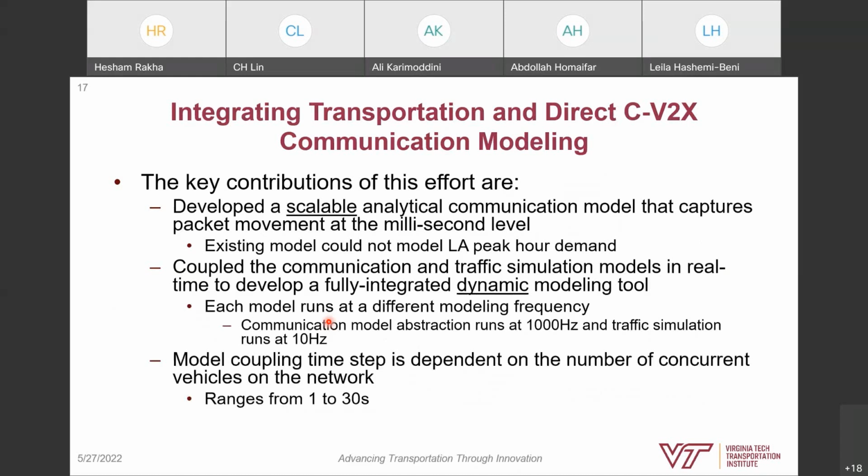We used an analytical model that was developed by some Spanish researchers, the lead author Gonzalez, in a paper, I believe it was in 2019, if my memory is correct, but I'd need to go back and check. But basically, we used their model and we had to modify it, because when they developed their model, typical of communication experts, they model it on just a linear system, so just one roadway that is linear. In our case, we're modeling it on a network where you have two-dimensional roadways. So you have some roadways perpendicular to this roadway and parallel to this roadway and along this roadway. So we have to take into account all the vehicles surrounding this specific vehicle in order to identify the possible pairs of vehicles that can communicate with one another.